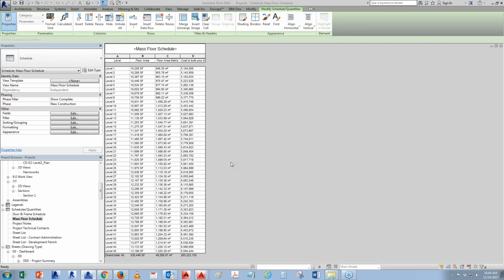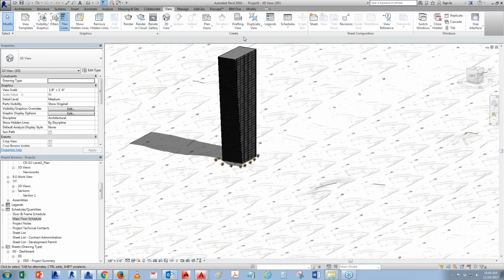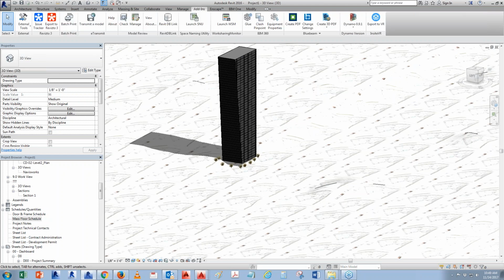Okay, it's not just Revit, we have a lot of other analysis tools. So let's say you're doing a massing, there are tools for that. There's a tool to do the energy study. There's also glass ratio, like how much glass you need for your building and so on. So a lot of the BIM tools are there for the user. If you have a requirement for certain things, it's good to do it within Revit because it provides you a lot of those tools that you can analyze, and you're not losing that data.